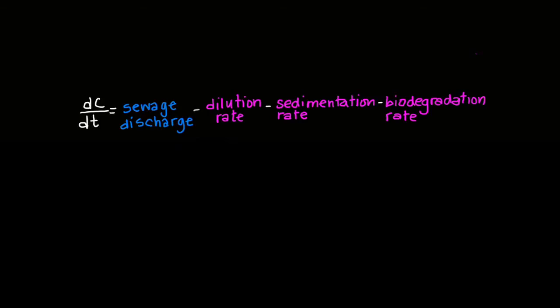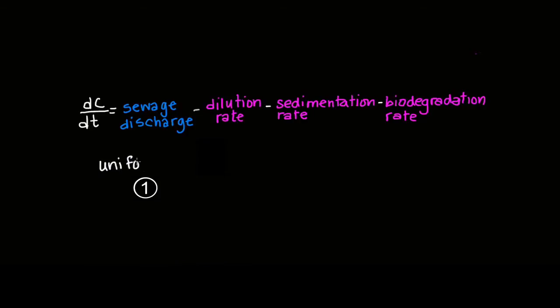We're going to make two more simplifying assumptions to make this equation easier to solve. Remember, the goal is not to have a perfect model of estrogens in the bay, but to make a quick computation to estimate how much water I should collect before I will have levels of estrogen that I can detect. The two simplifying assumptions we make are that 1. The distribution of estrogens in the control volume is uniform. That is, the bay is well mixed. 2. The concentration is constant in time. That is, the inputs and outputs are balanced.